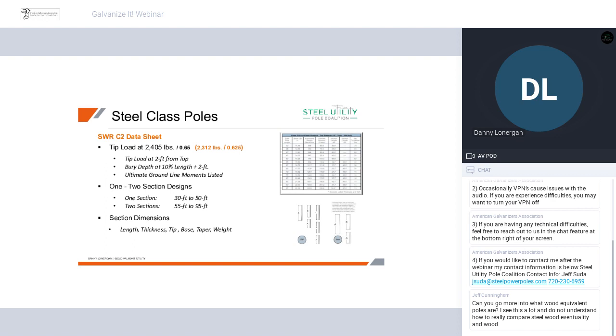Typically, what you won't see in a predefined structure or in a catalog structure is its deflection. And that's typically the case because the true loads to the structure are not known. So it's the responsibility of a fabricator just to communicate this is a pre-existing structure and its shape and dynamics and our section properties look like this.